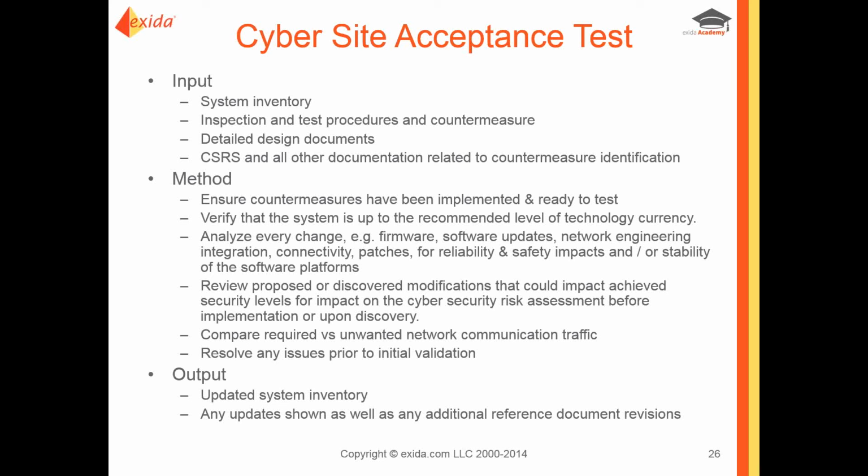Coming out of the cyber site acceptance test, you may find that through changes, you want to make sure that your system inventory is fully up to date, and all of your documentation should reflect the as-built that is commensurate with the security level that you want to achieve.